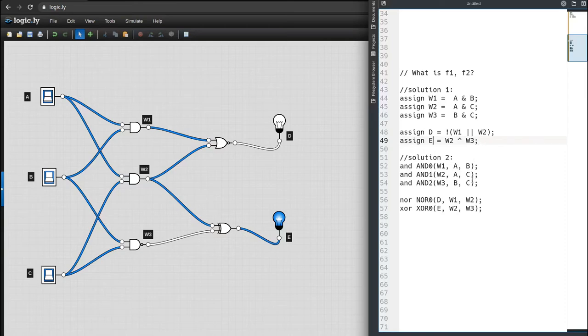Another way that I want to do in the tutorial today is use the built-in functions in Verilog. So in Verilog, technically what you're doing right now is writing a function in terms of a module. Verilog already has some built-in gate functions or built-in gate modules that you can actually use and implement. The gate module has a convention of output first, then the rest of them are inputs. So this is what we're gonna do.